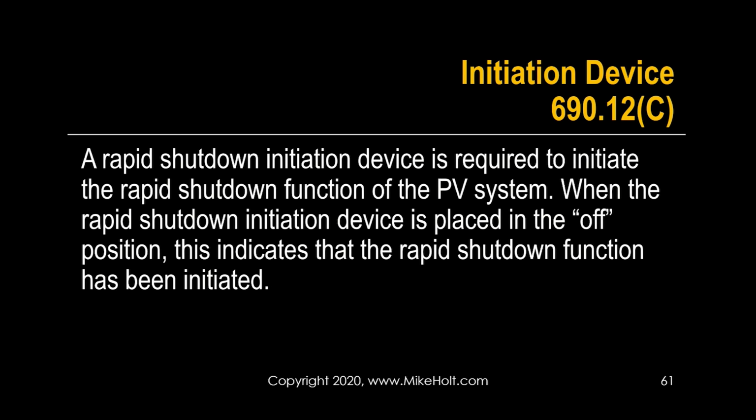So hold on. This person's question is that the exception is only for PV output circuits. The leads coming off the modules are part of the PV source circuit. PV source circuits are required to have arc fault detection regardless. The only exception in the National Electrical Code to arc fault detection on the leads coming off a PV module is in 691, which we'll cover later, which talks about having a fire mitigation program. So all PV systems that are not part of a large-scale system must have arc fault detection on the source circuits. No exception.